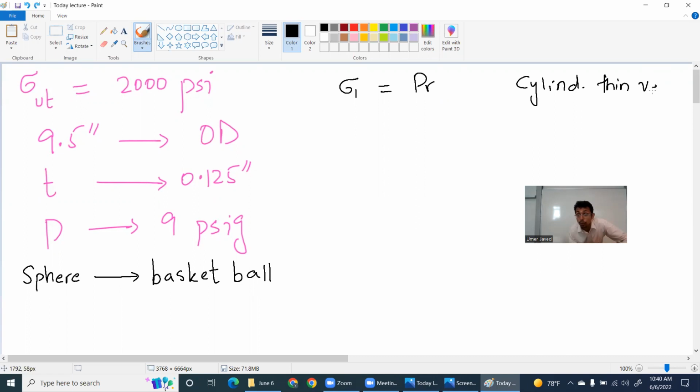So we have circumferential stresses, which are known as hoop stresses. Look at the Coca-Cola can, and you have circumferences like this. These are stresses along the circumference. We're going to call them hoop stress, but circumference is a word that you know better than hoop.